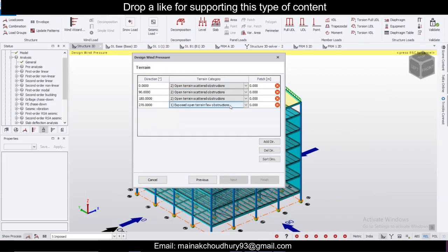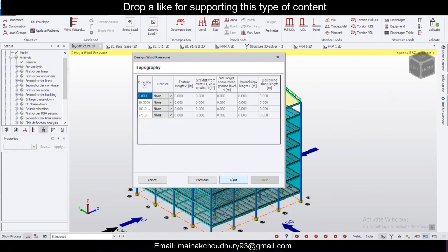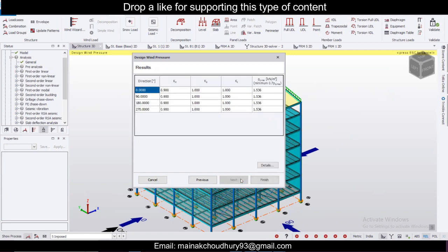So according to which this will take, and the fetch distance is basically the distance at which the wind is the same or the atmosphere is the same. So generally we take it as 5 meter, so no problem in that. Okay, and the definition of the fetch distance is also given in the IS code, so no problems in that. Click on next, and here if you want to add topography feature, you can add. If any topography hill, you have to give the details, but if you don't want, then you are not required. Okay, then click on next, and then click on finish.